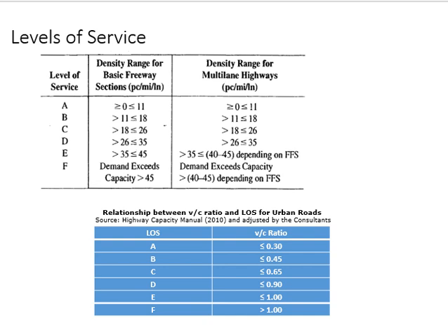This is what is given in the Highway Capacity Manual, the first table. So you can see the range for each level of service. This is the range of density I was talking about. And what is the last value here in the table? What is the last value of density? 45, right?